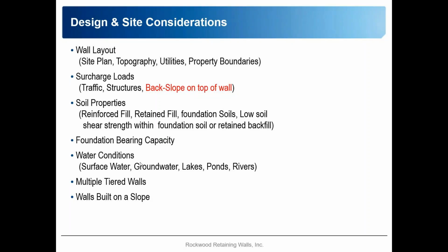Yes, we do have drain rock behind the wall, but retaining walls are not designed to be a drainage system for the site. And it's interesting, I just had this conversation with a developer Monday of this week. They were saying, well, yeah, but you have all this rock, so what's wrong with the water from the parking lot being drained toward the wall? Well, the drain rock that's there is intended to assist and reduce the amount of water buildup behind the wall and poor soils being contained, but we're not trying to divert water to retaining walls. That's never a good idea.